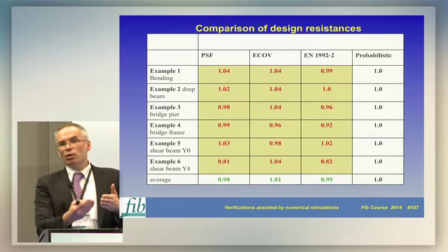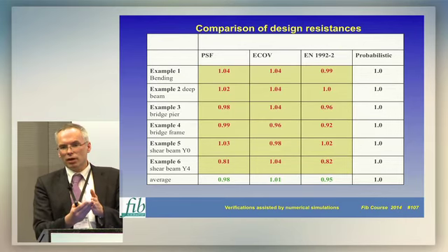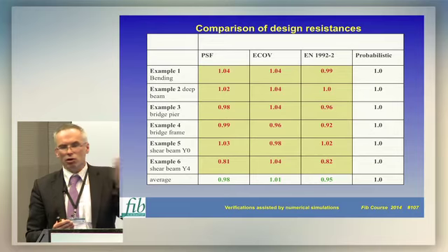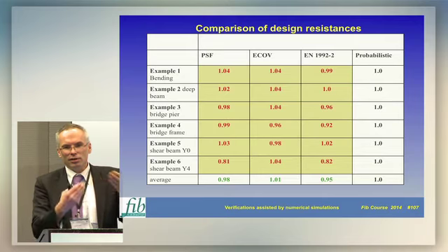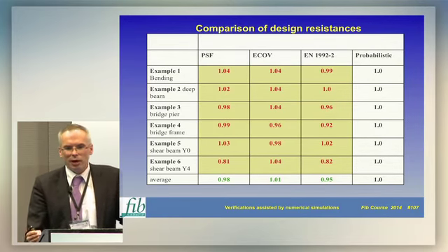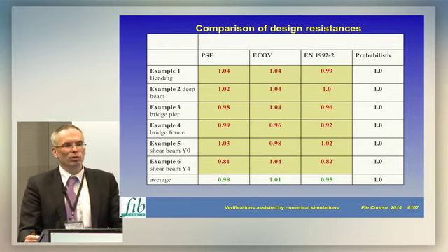Because also if you think about this method, what this method is actually doing is that as you increase the load to the design level, it checks all the sections. So it actually is doing what the standard design is doing. That it is basically checking all the available sections, even those that you would not check normally.